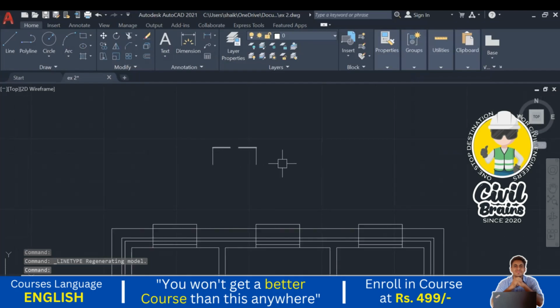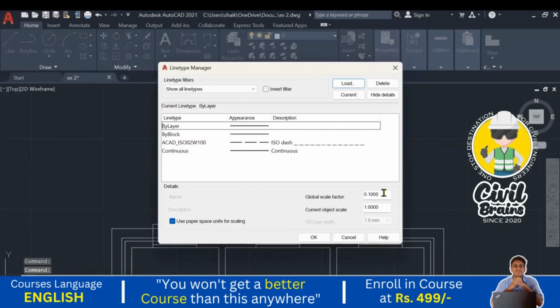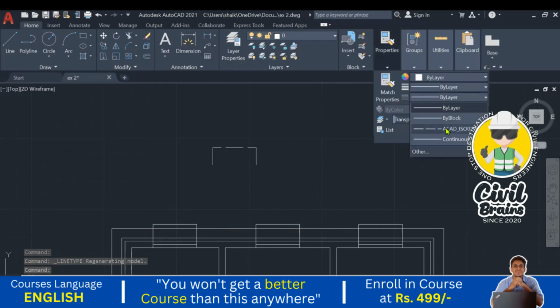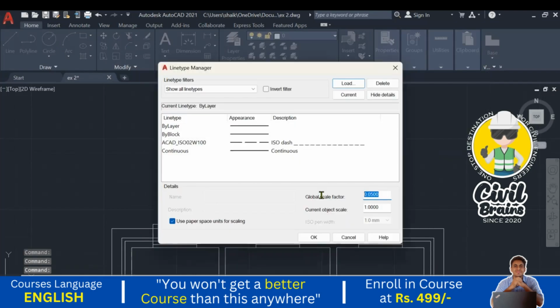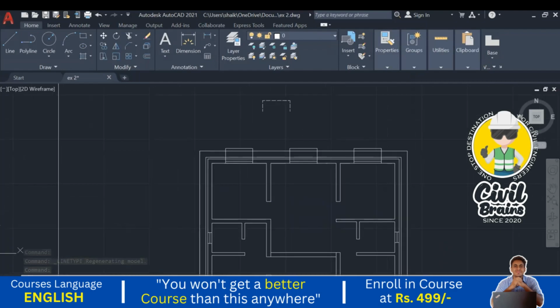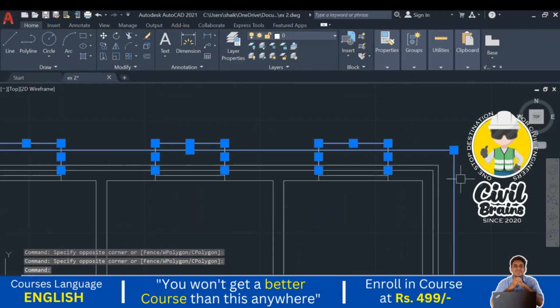Here you can see this one. Now small dashes came. Large dashes came. Again, I go to the section. I go here. I change the scale. 0.05 I make. I check. Okay, 0.05 is also very large. I go here. 0.02 I take. Press OK. Okay. 0.02 is the correct one. So now I select all the chajjas and the slab projection, and I make them dotted lines.